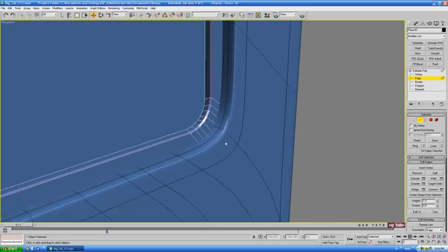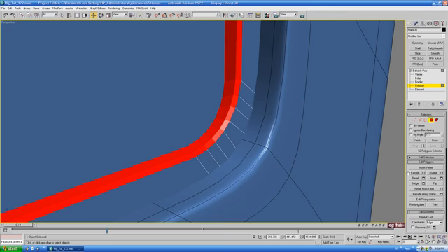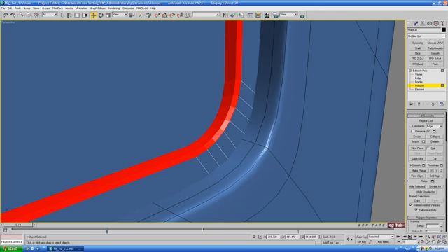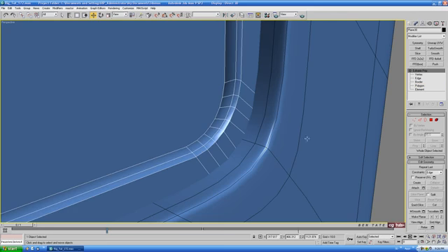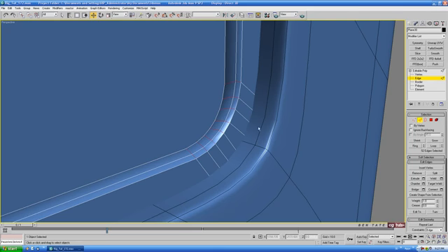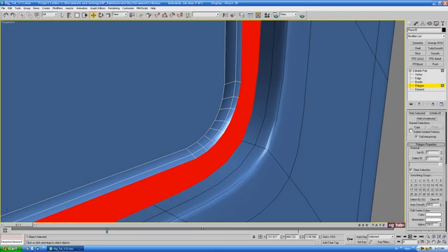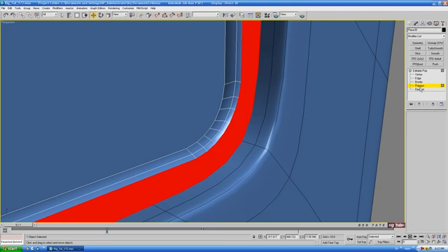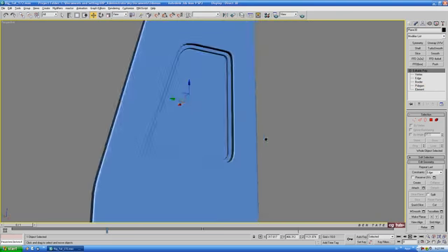And you can see it looks a little bit rough there in the corners, so if you want to, you can put a smoothing group on there. Let's just maybe do that quick. Just going to grab that edge there as well as the one on the chamfer. We'll ring them. Control-click polygon, and go way down in the modify panel here to the bottom. And we'll just put that on smoothing group 1. Okay, and let's maybe do the front ones as well. So I'm just going to grab a front edge, ring it, control-click polygon, and we'll put this on a separate group. Let's do this on maybe 2. And we'll turn off polygon. That'll just smooth it a little bit for us, so it's not so faceted.